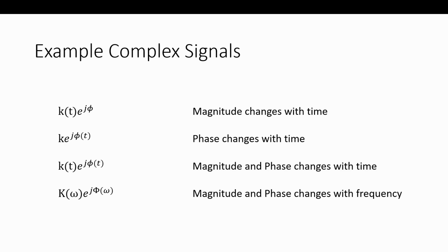But there's a lot of paths that get confusing, especially when we get to carrier recovery and timing recovery. Two separate things in the receiver. One works on phase, the other one works on time. Two independent operations. And so that's an important takeaway.